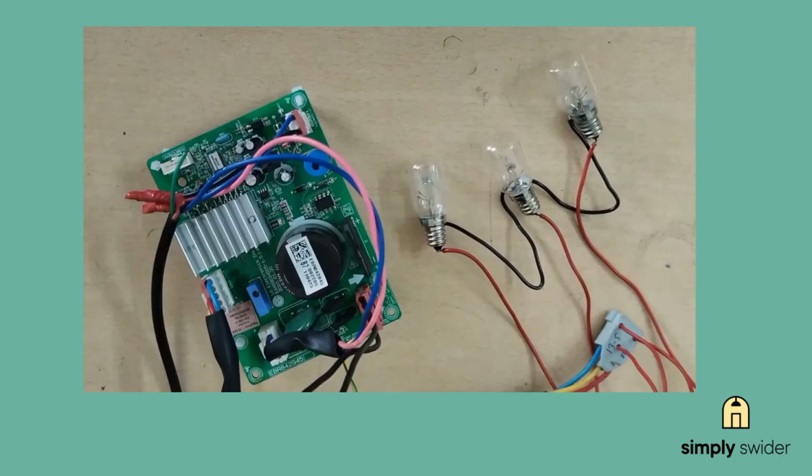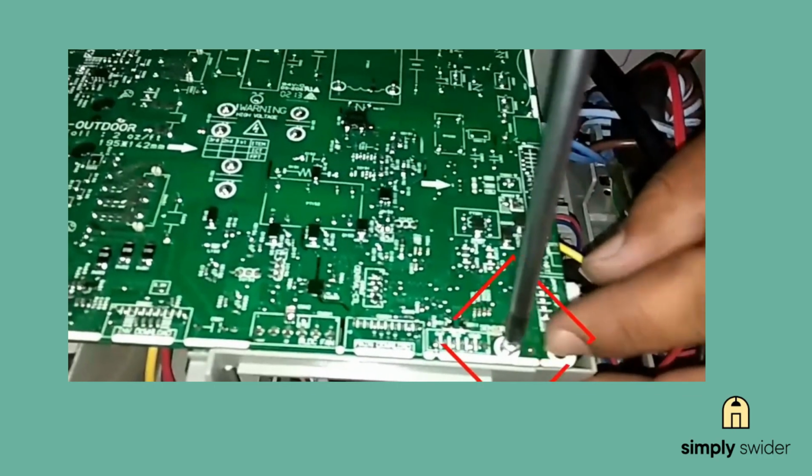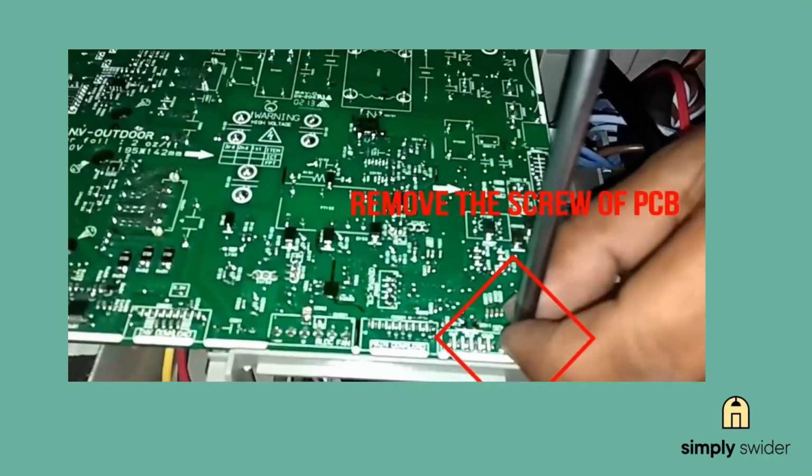Here's how you can check. If you're comfortable around electrical, you can test for voltage output to the compressor during startup. Those UVW terminals, if you've got 0 volts but the board's powered up, your inverter drive circuit is toast. Visual inspection works too. Look for obvious burn marks near the IPM module or IGBTs on the outdoor board.